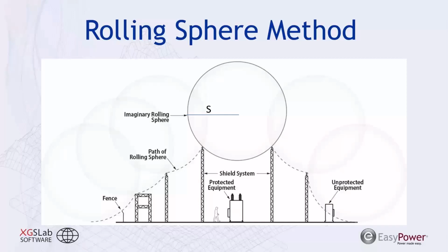If the return stroke current was of insignificant magnitude to cause an outage, we don't have a problem. However, if it is significant enough that it exceeds our insulation levels at our utility substation, we could have an outage at that substation, and that could be a critical issue for us as we're trying to maintain power for users in a storm environment.